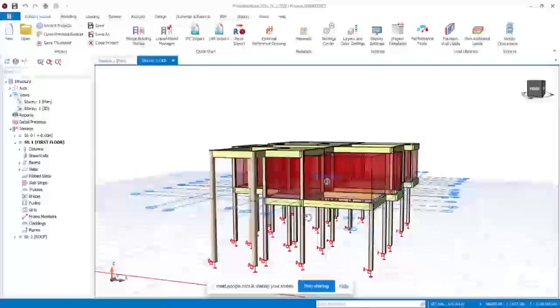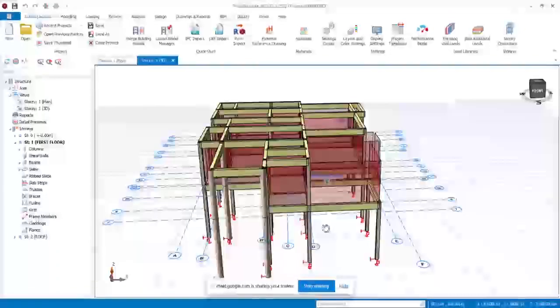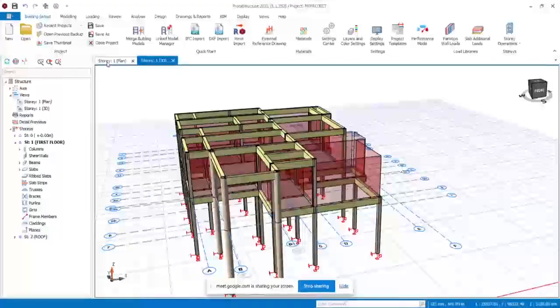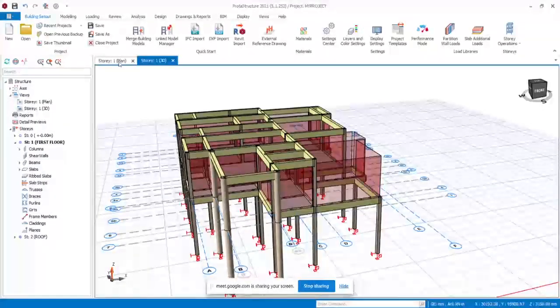Yes, sir. Please, how about walls that did not pass through the beams, that pass through the slab? Those are exactly why we use partition. You know, I spoke about partition 1.5 millimeter per meter. In the design of your slab, we cater for partition. So those are partition walls and not main walls that are supporting beams. So that's how we use partition. All right, sir.